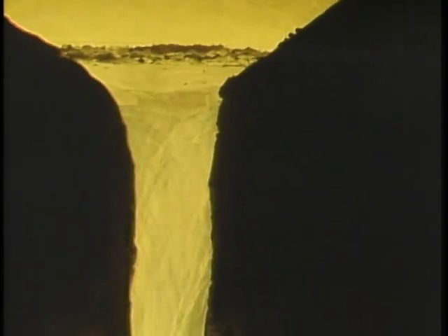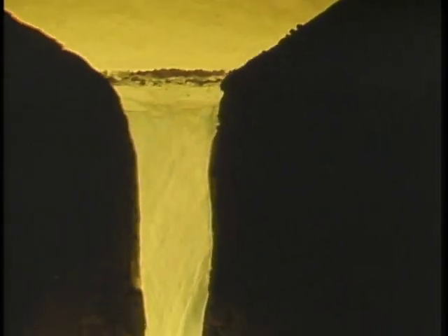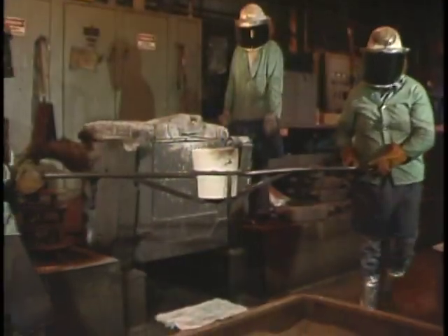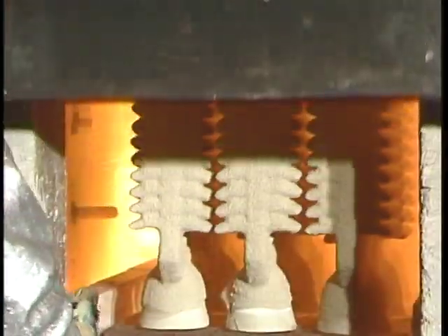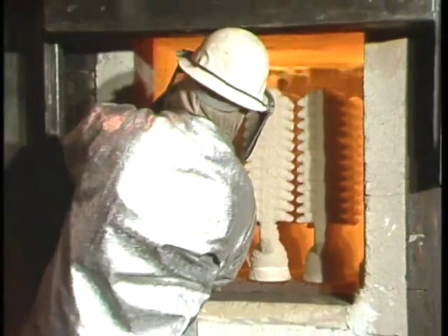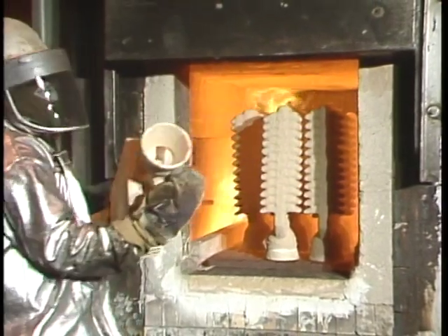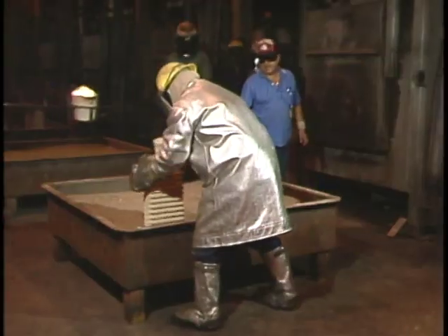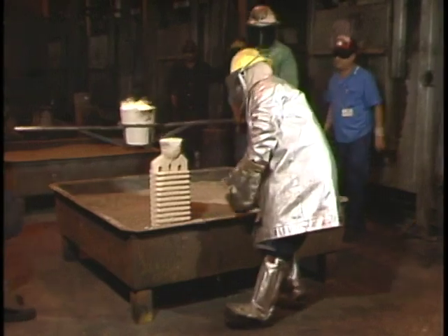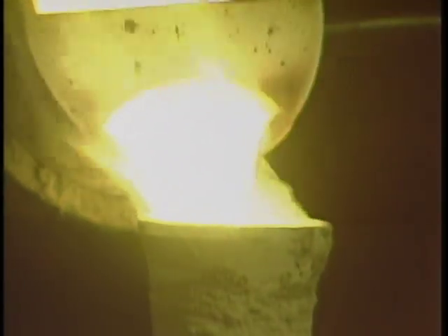It is then poured into the preheated shells and allowed to cool. Different types and sizes of ladles are used depending upon the size of the part to be cast and the alloy being poured. In some cases, the shells are placed into fluidized sand beds for pouring. Light alloys are generally handled quite differently. While a few light alloys are air melted, many others are melted and poured in a vacuum.